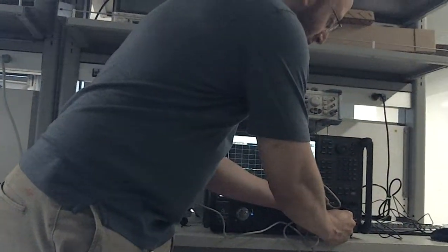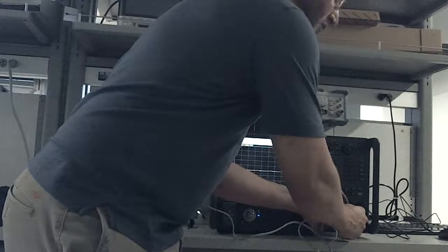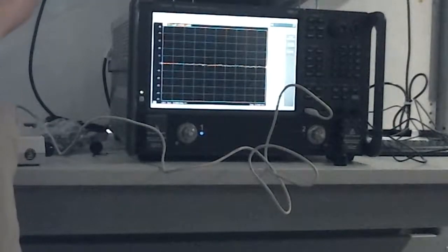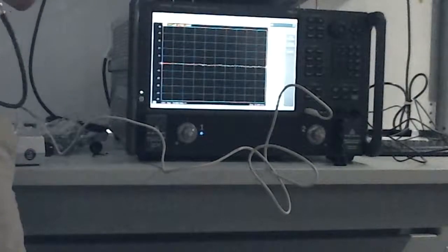The other thing that you want to do, right, is you'll see there's a male and female part of the connection. You always turn the male outer nut, right? So, if you think about that, why am I not turning the female part of the connection? If you take a look at the bullet, or if you take a look at the cabling, you have an inner conductor, and then you have an outer mechanical jacket.